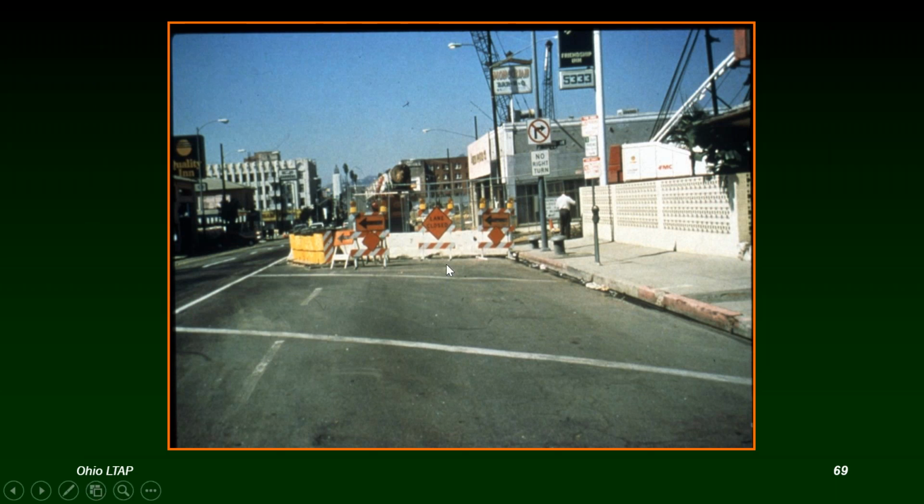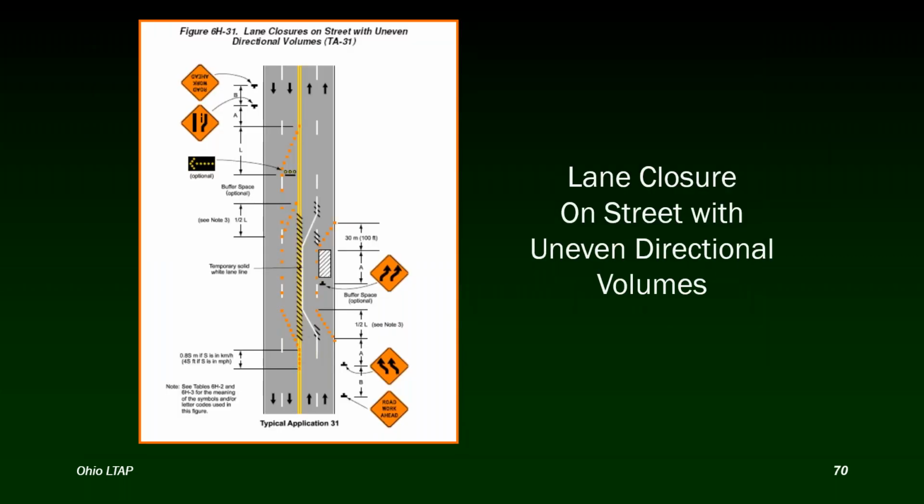This is not the way to do it. These lanes were closed, and they just sort of made a dead end and put these arrow signs here. This is a situation where they should have had a long, either one merging taper or back-to-back merging tapers.